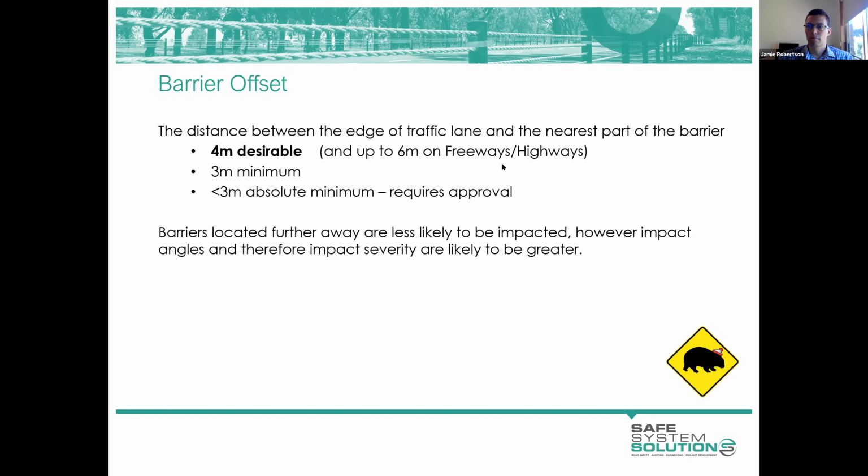Yeah. And the next question is coming from Mitch, around that 3 metre minimum you've got in there, asking if that's from Austroads guide and should it be applied to retrofit situations where practical? Yeah, Austroads nominates 3 metres as a minimum or desirable minimum offset.